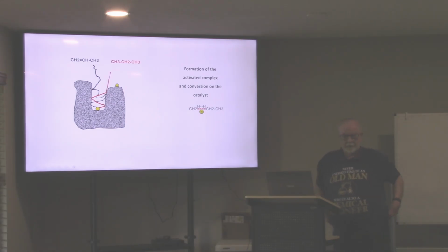And this is just to show you, exaggerated, this is more like what's really the case, that the molecule, the black one, that's the reactant coming out of your engine. And it would come down and shake around in there until it sees platinum. Then it's turned into the red molecule and diffuses out.